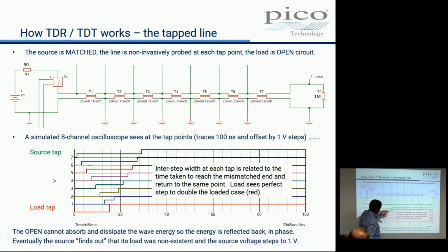It knows the difference between that green line going on straight and that green line going up. If it goes on straight, we had a 50 ohm resistor at the end. If it goes up, we must have an open circuit at the end. Yeah? So we can find faults on cables, and we can find the impedance of things. We can find out if that's a 75 ohm resistor. We can do all that stuff. And if anything went wrong in this cable, we'd see it on here. So it's a kind of a network analyzer, isn't it?